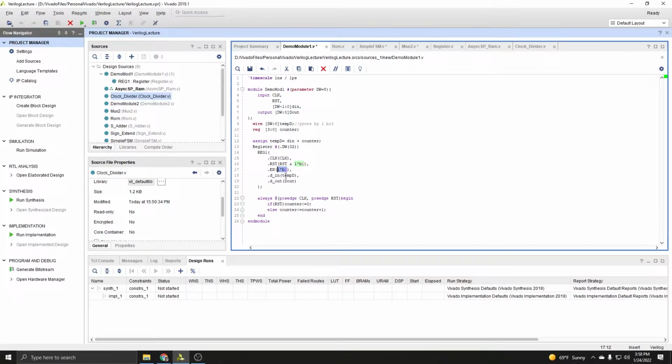So like, let's say there's a signal that is already declared somewhere that's called clear, and then you have your normal system reset. Well, you can have it such that it resets either when reset or the clear signal are high. Now, of course, it's going to give me an error right now because I don't have a clear signal declared anywhere, but